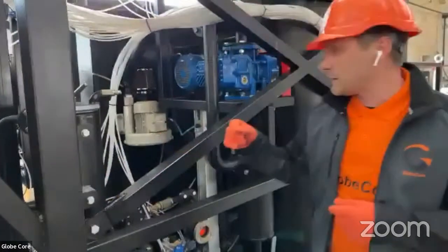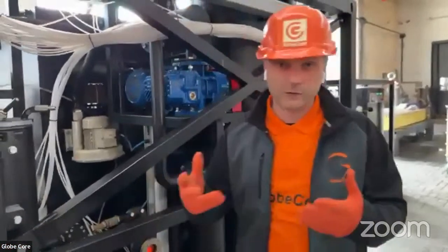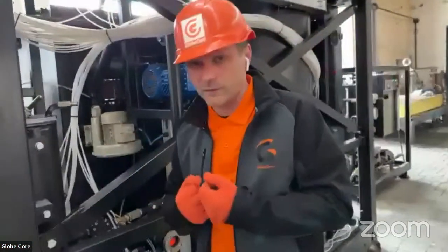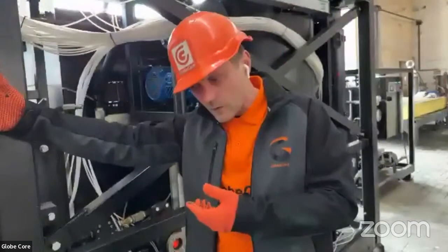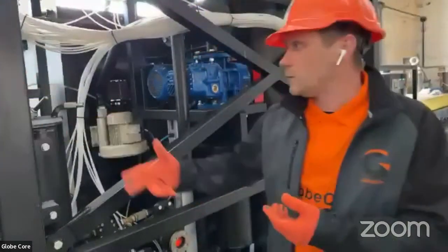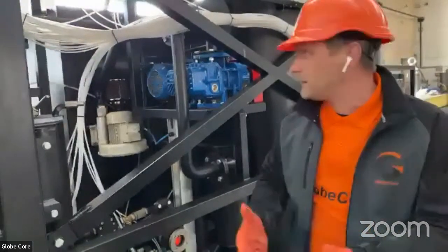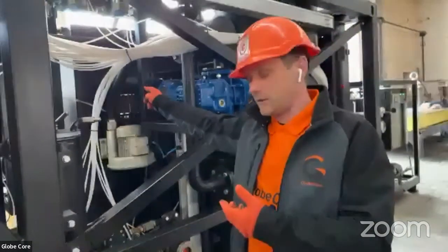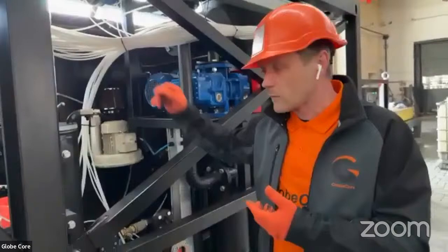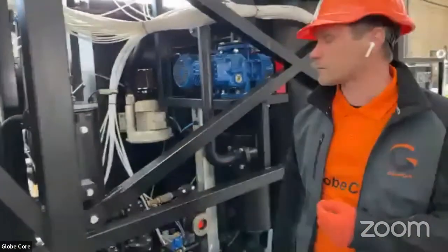It is very important when you work with the transformer, because in fact you cannot take oil from the transformer, because it will decrease the level of oil in it. So if you work with the transformer, especially with the transformer online, you need to have the buffer tank on board of the unit to refill the system.